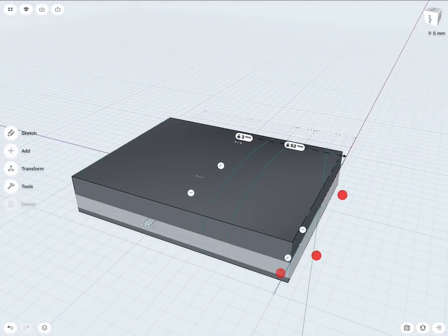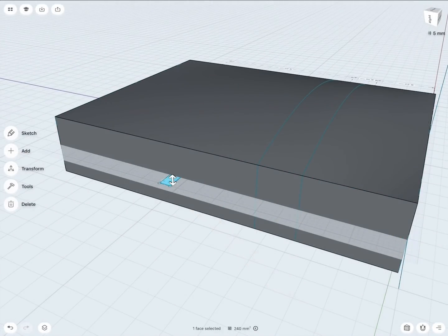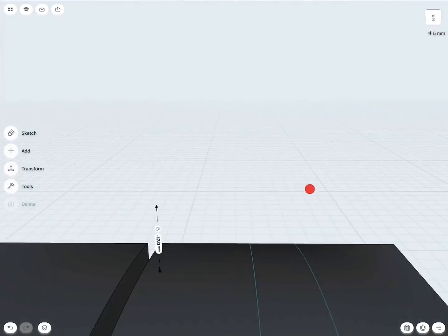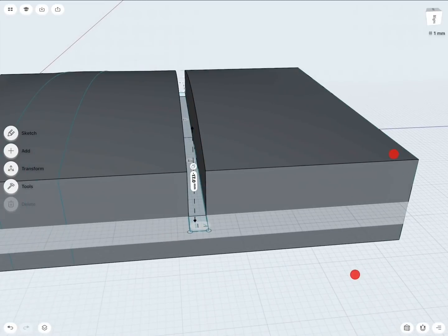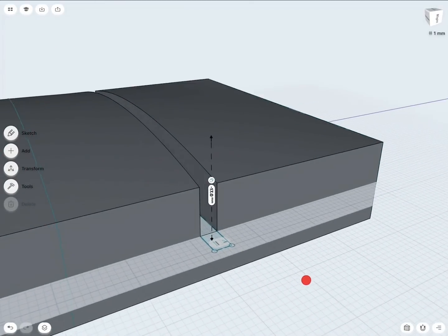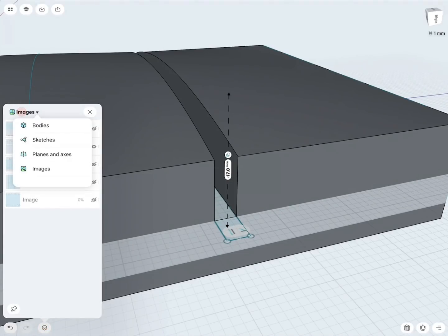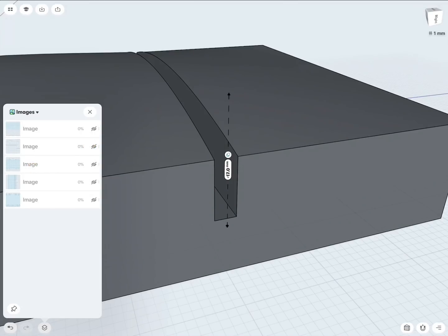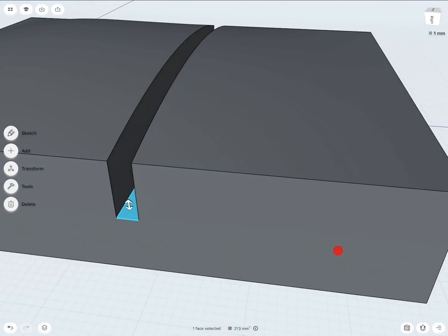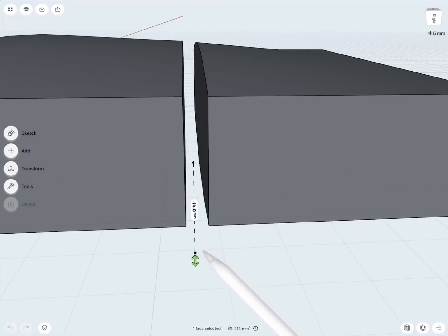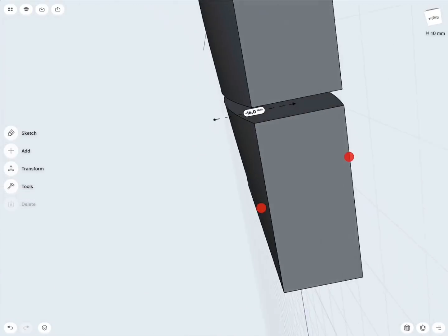We have to do the cut. Okay, not a big deal. Let's do a push and pull. So I don't necessarily here use the extrude command. I simply select the sketch and then I cut it. Let's go to sketches, and I would like to turn off these sketches so we don't see them. Let's go to the image plane, turn this one off. Very nice. I select this face now, and then via direct modeling, I simply move this face till it's out and it is cut. Very good.